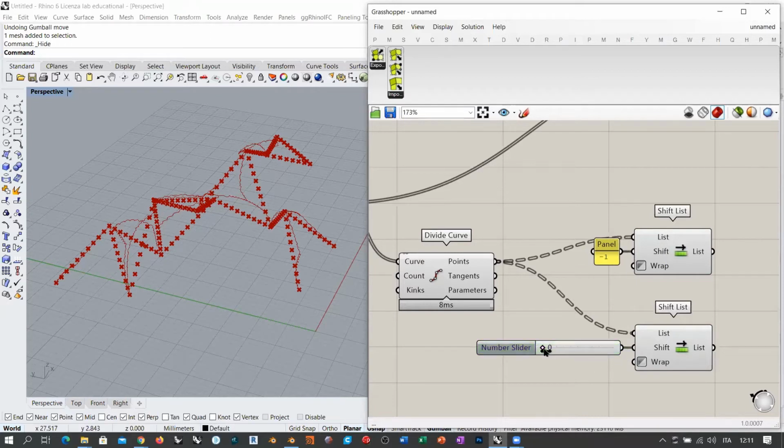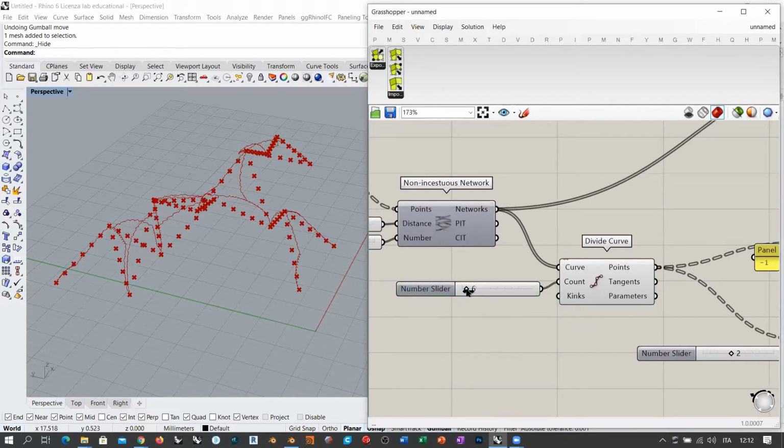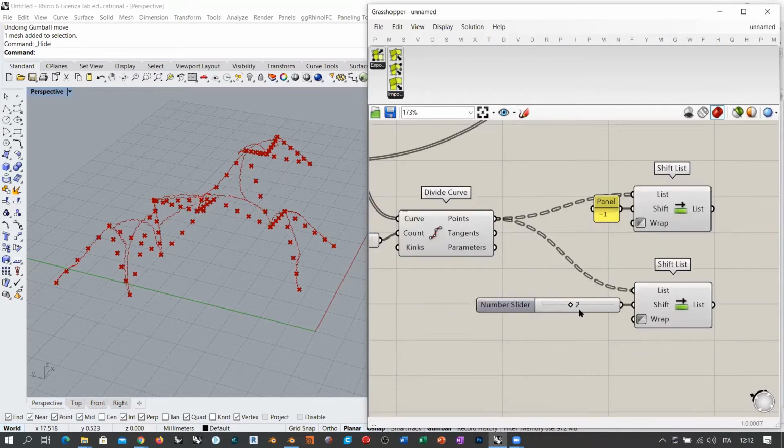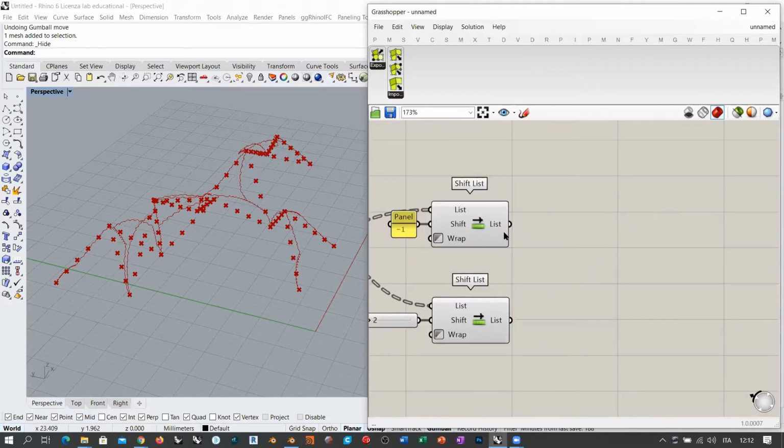Remember this thing that we did yesterday: if you want the fibers to move away from the path, like perpendicularly, then you use a low number. If you want the path to align along the desired paths, then you increase this value. Also remember that the amount of points is quite important. So let's grab a slider and decide if you want less or more subdivision. Let's work with a few subdivisions, and let's leave this at 1 or 2, because with this separation, 1 and 2 means already moved forward along the path. Okay, and so we have these.